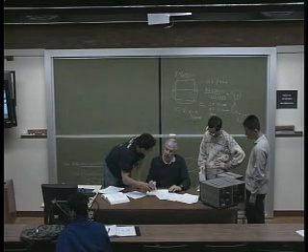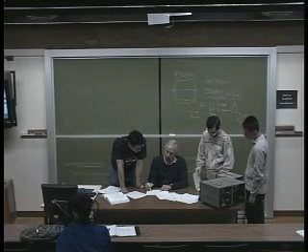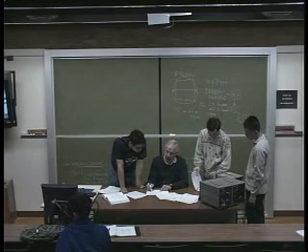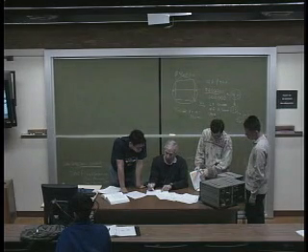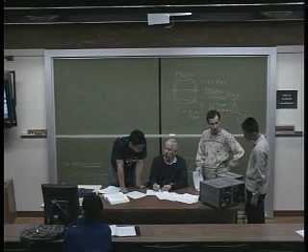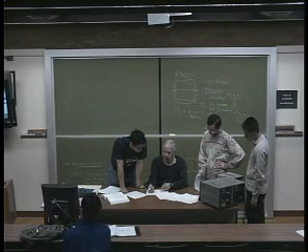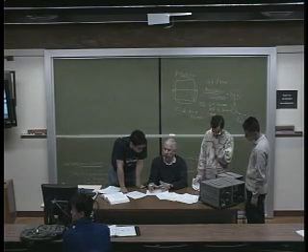Yeah, so this thing's feeding back around. So the feedback is coming into this node. Let's say this voltage is sitting way up here. Well, this voltage will come back here, and this voltage will rise and start to become equal to the voltage on this side. And when that finally happens, the differential voltage drops to a very small value again, and we're back into linear region operation.